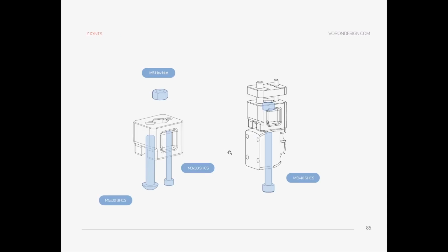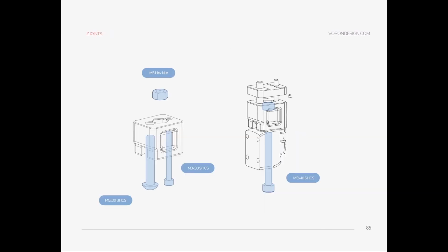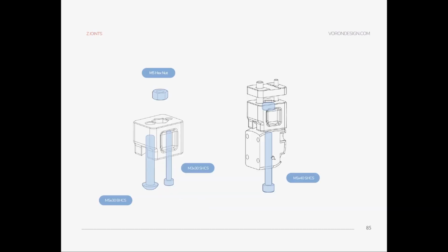In here, it's a little bit confusing. What I would recommend is to just build these two stacks. Put your hex nut in here and put your cap in here. With these two parts, install them on your gantry, I mean in here. While installing this one, also check your Z belts first. They should have the same length. You can use the tooth method that I showed.